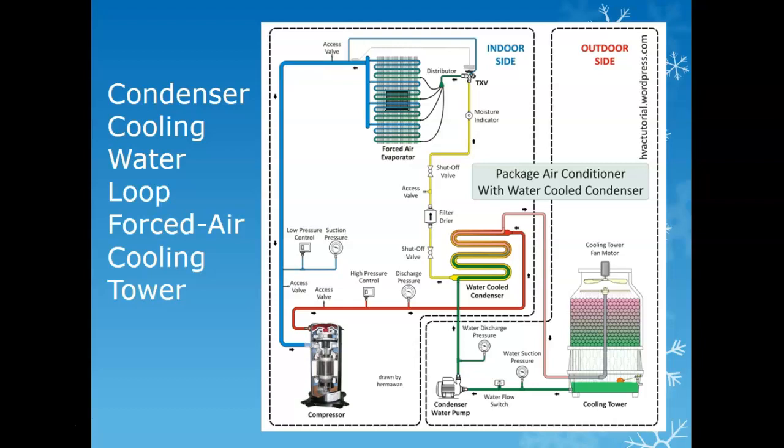If you got something that's really super cold, essentially all you have on what's going on, okay, I think I know what you're asking. So let's say you had frost on these lines. You're asking about that, right? What is going on is that the internal temperature is so cold that it is actually freezing the moisture that comes in